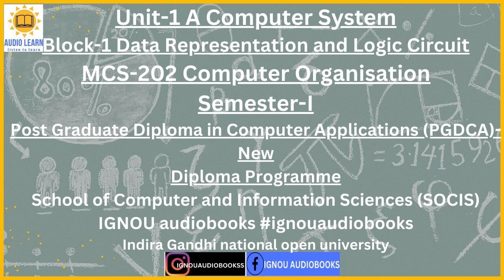Interrupts and the instruction cycle. The interrupt process is summarized below. The CPU is executing a program, say X, and is in the decode stage of its I-th instruction of the program X. Assume an interrupt due to an event occurred at this time. The CPU waits till the I-th instruction execution is complete, and then stores the register value in PC, which has the address of the I+1-th instruction, into memory or a special storage area.